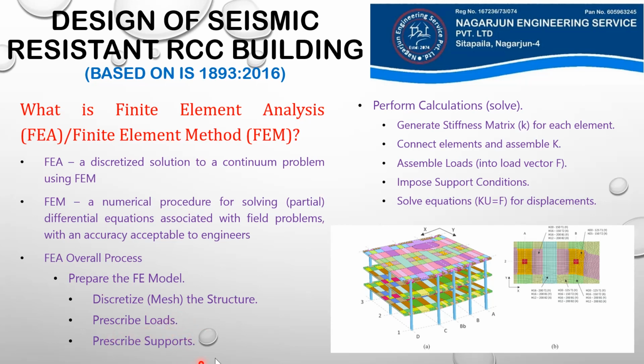We have to prescribe the supports, what sort of restraints or constraints that we find in this structure. And once the modeling part is complete, now we will perform calculations to solve those partial differential equations, and this will be done by the software itself. For performing those calculations, the software generates stiffness matrix for each element.